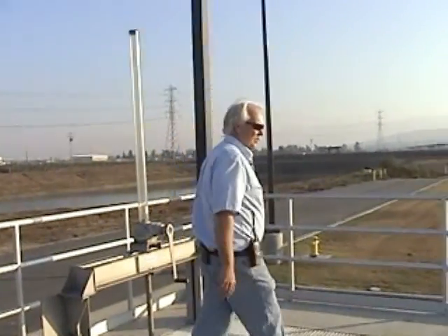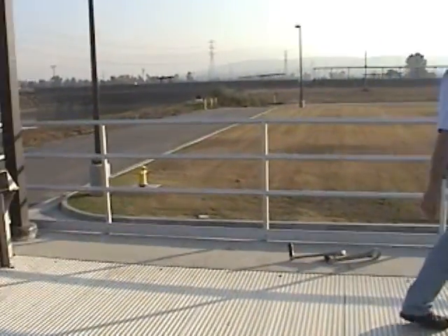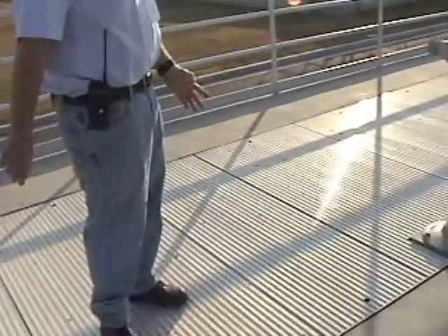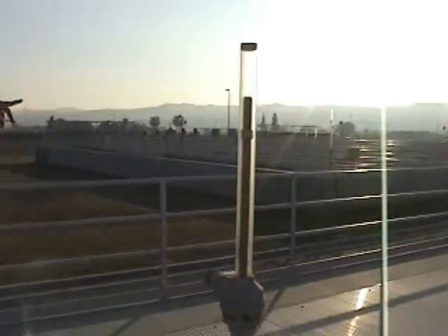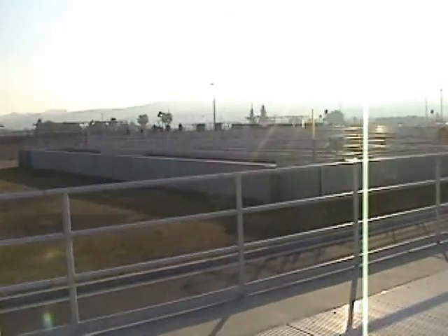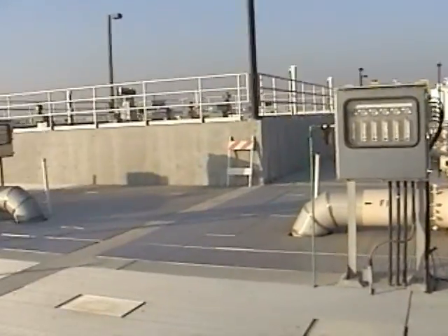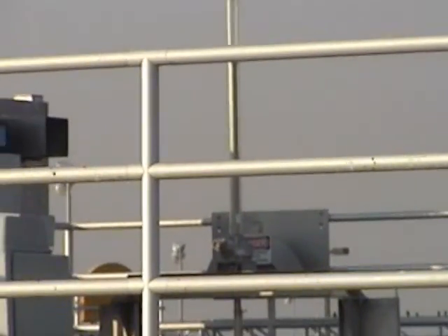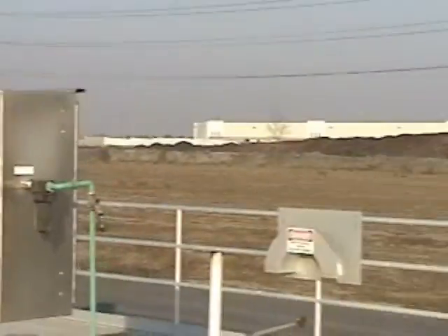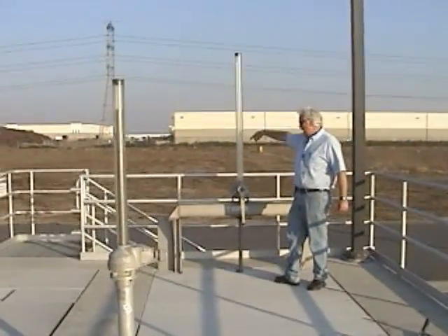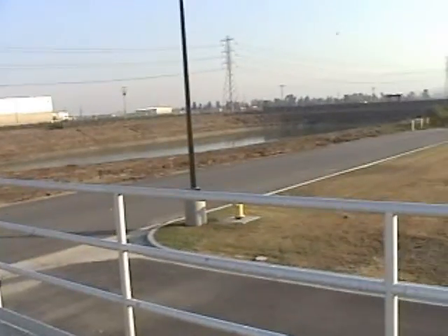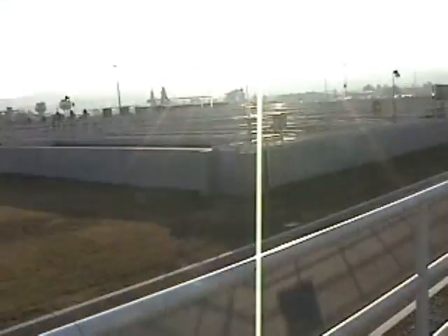This right here, the discharge points for the filters are right here. They're going to flow into this channel, and then from this channel they'll flow into the chlorine contact tank over there. If you want to bypass the filters, you can close that gate valve up there. You would close that, and you would open this, and the flow will then go around the filters and straight to the contact tank. You'd never want to do that unless you consulted with a lot of people, because bypassing the filters is a violation of our permit. So if we're discharging, you're out of compliance for Title 22.